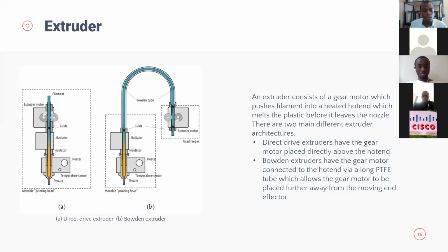I told you that you can regulate the temperature of the print head. That is where you put the temperature sensor. It measures the temperature, how hot or how cold the head is. That is what we use to regulate the temperature. So when it goes very high, we reduce the current flowing through the filament, and otherwise we maintain it at a specific temperature.